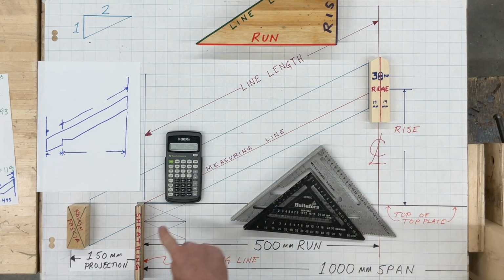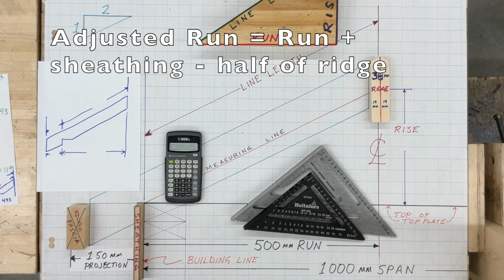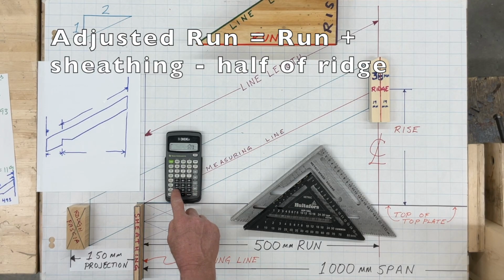In this example, we have to calculate the runs between the face of the ridge board, the outside face of the sheathing, and the inside face of the rough fascia in order to get the line lengths between the cut lines. To our 500 millimeter run, we'll need to add 12 millimeters for the sheathing and subtract 19 millimeters for half of the thickness of the ridge.